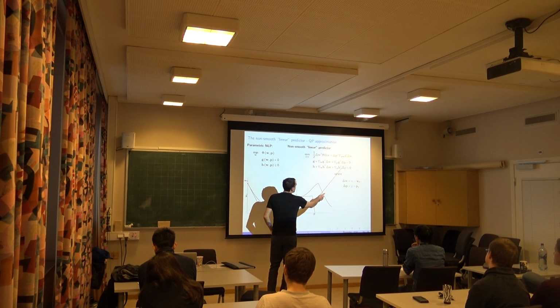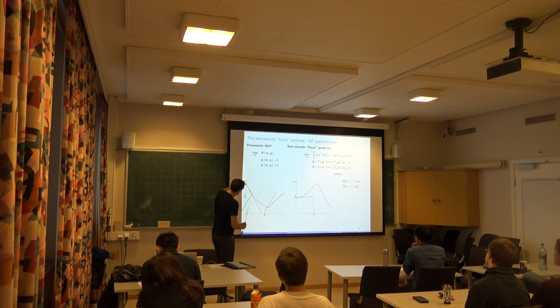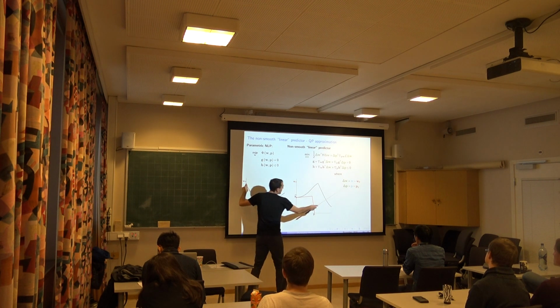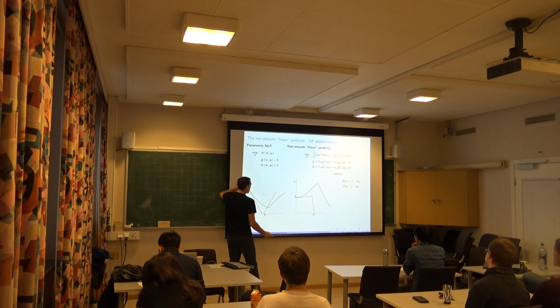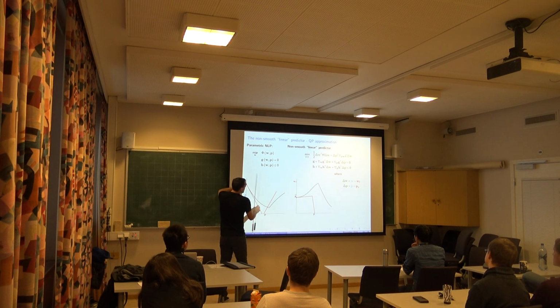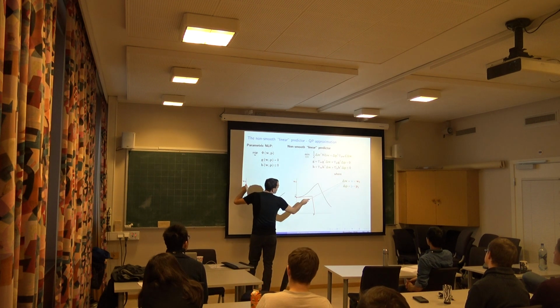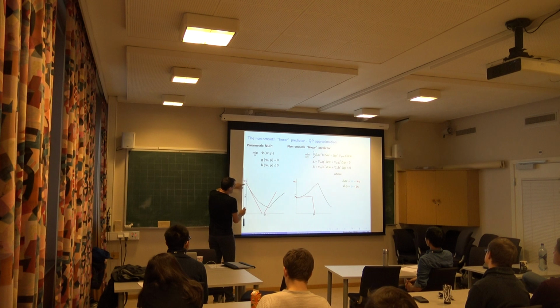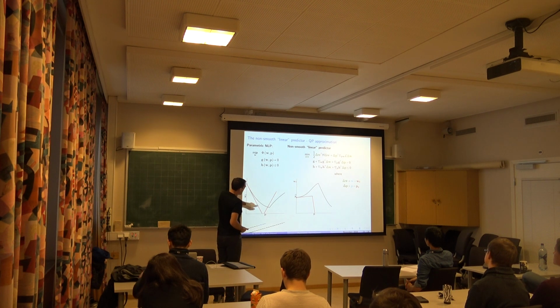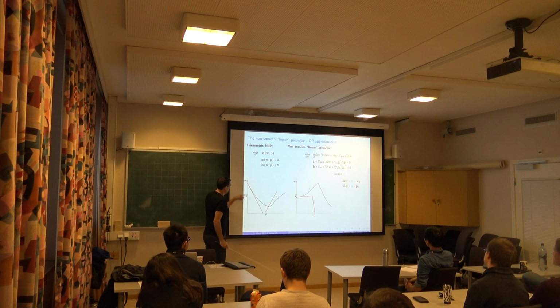And then I play around with this delta P. So I can say that delta P0 here, and then I move P around, so I have different delta P. So P0 is this point here, and if I want to try different P's, that gives me different delta P's. So I could solve my QP for these different delta P's and get the correction delta W of my W0. And if I do that, the QP will actually be something that looks like a linear predictor, but it will actually also see changes of active sets. If I do it at that point, I get this picture here.